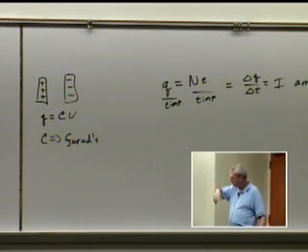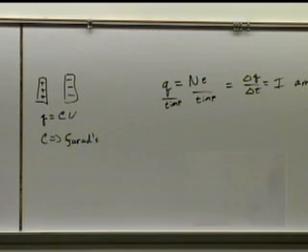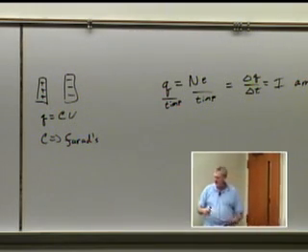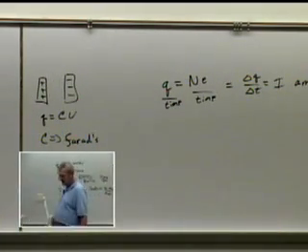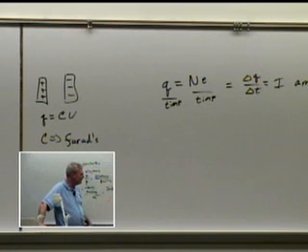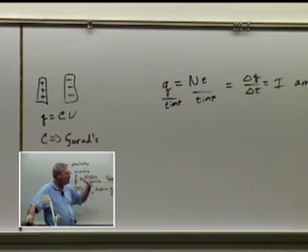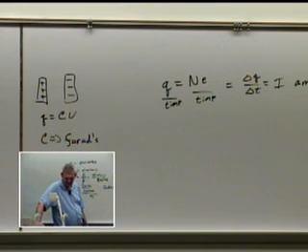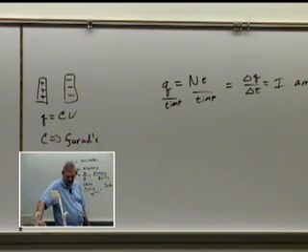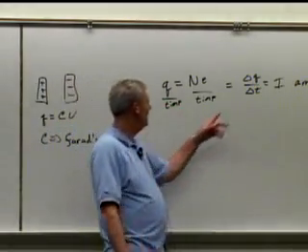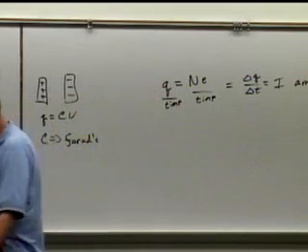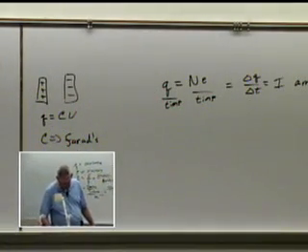I mean, there's definitely a difference in the positive and negative charge. You're all negative and this is all positive, so there's a difference of 40,000 volts, possibly, but the amount of amps, the amount of coulombs isn't that great. So the amount of amps or charge that's going to flow in a split second, really a split second, is very, very small. So that's why it just kind of bites a little bit, or maybe you can't feel it at all. Okay, so that's the way we measure current. Current is the change in coulombs divided by the change in time.